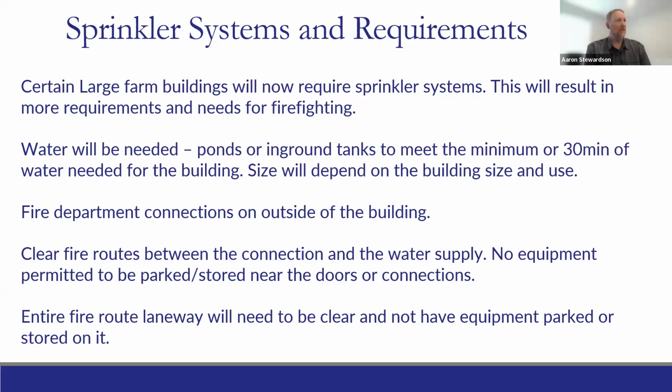Now, just keep in mind with all these requirements here, sorry about that, is that these are large farm buildings, right? So over 600 meters squared, 6,400 square feet. Okay. Fire department connections are required on the outside of the building when we get into sprinkler systems, right?